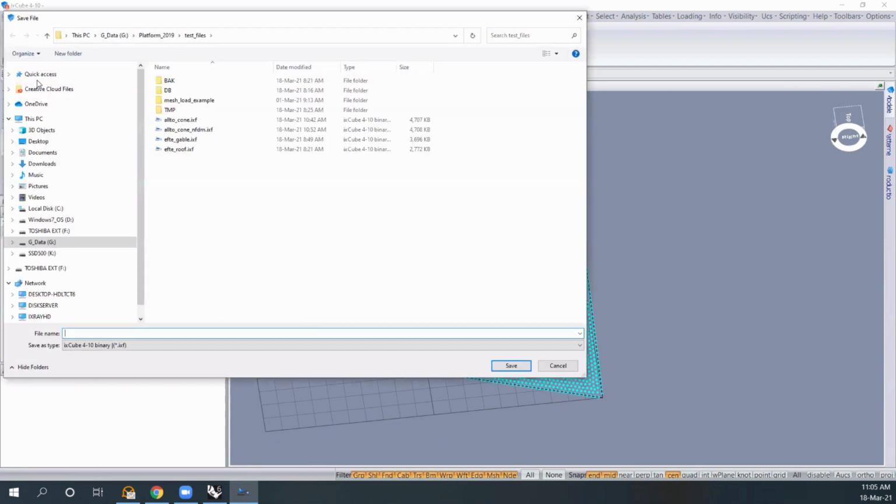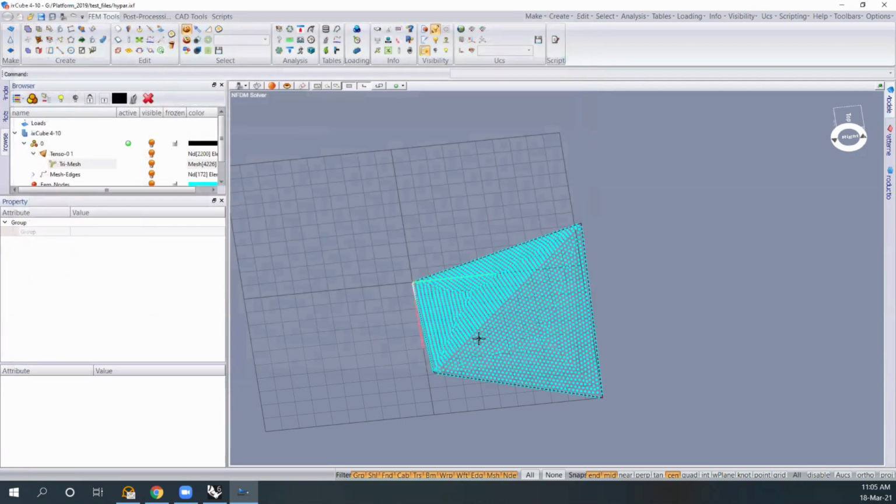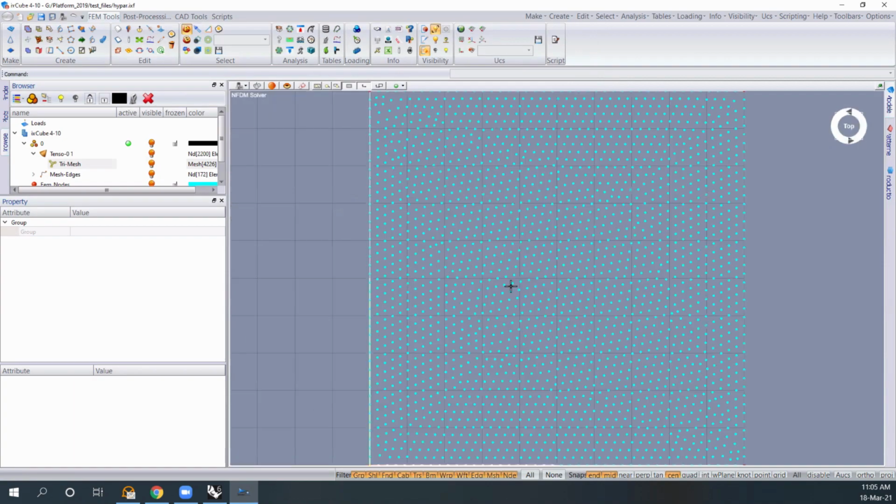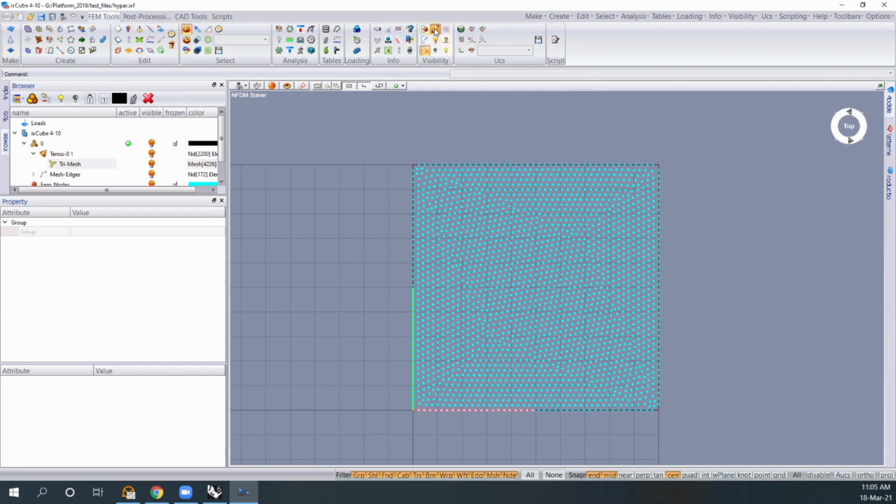There's one thing that is missing, and it is one thing that I didn't even tell you in the force density method. What is warp and what is weft? In the force density method, we have a net where the direction of the fibers tells the software what is the warp direction and what is the weft direction. Now we have a finite element triangle mesh. And so how can we tell the software what is warp and what is weft?